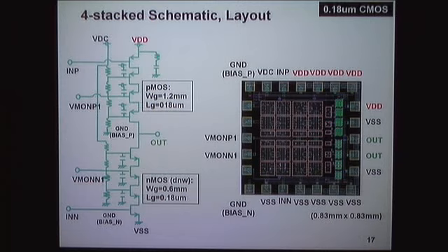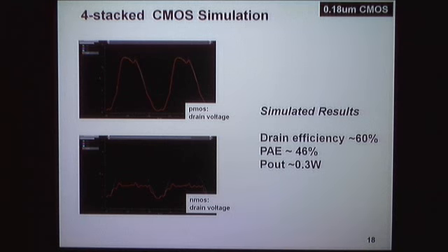in a CMOS process. So you end up stacking them up 4 ways, both top and bottom. So you have 4 P-channel devices stacked with 4 N-channel devices. In this way, you can keep the voltage across each reasonable, still have a reasonably small die, and increase the voltage. So that's a very nice thing. You can do this while using a relatively long gate length because it's inexpensive to go out and do this. And that's part of our motivation here, that you can even use this relatively long gate length process that costs a lot less than TSMC and has quite a low lead time.